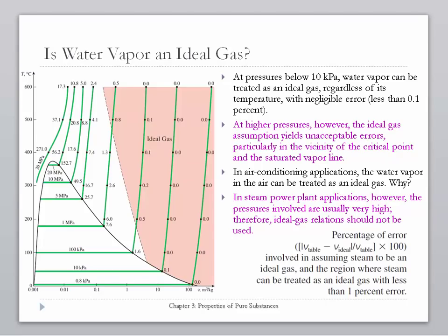One of the things that we have mentioned in class is that vapor is not the same thing as a gas, and this plot allows us to realize that. For example, this is the plot of temperature and specific volume for water. As we know, as the temperature increases, the water is going to become a vapor. So all the area that we have in this part over here is going to be your superheated vapor. As the pressure reduces, notice that you get to this range over here, the red range, and that is going to be your ideal gas.